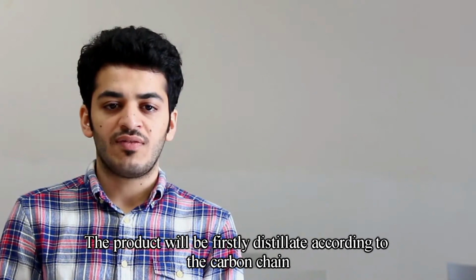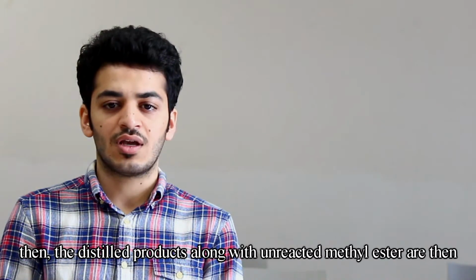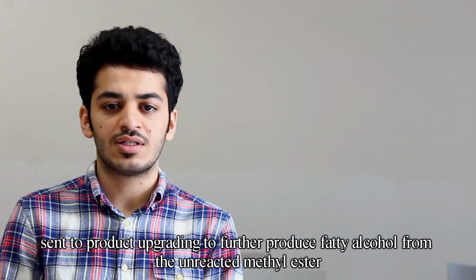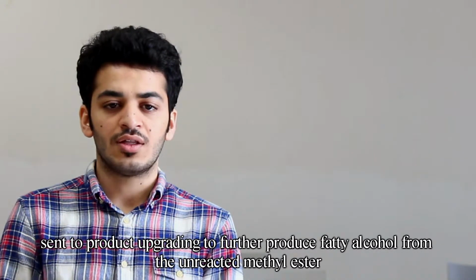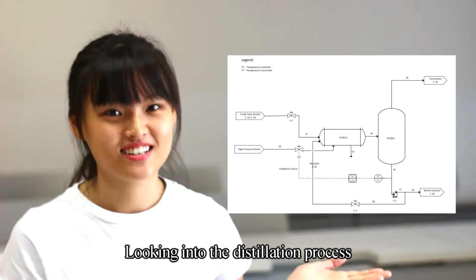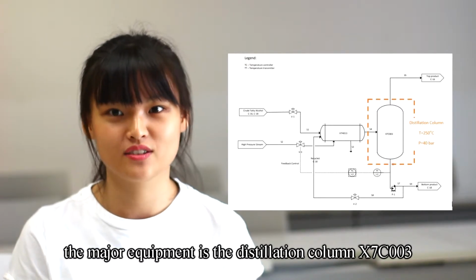The product will be first distilled according to the carbon chain. Then the distilled products, along with the unreacted methyl ester, are sent to product upgrading to further produce fatty alcohol from the unreacted methyl ester. Looking into the distillation process, the major equipment is the distillation column X7C003.